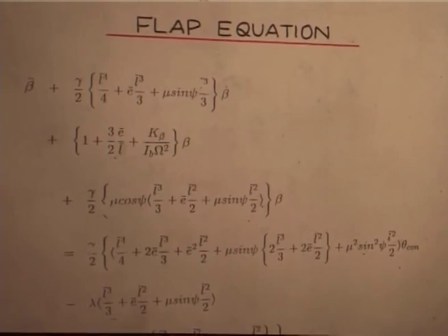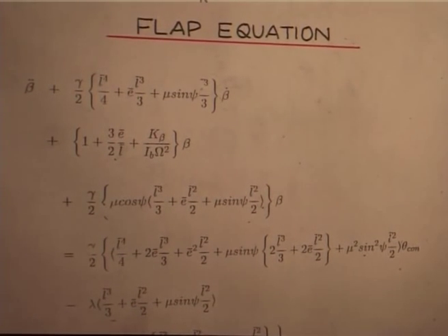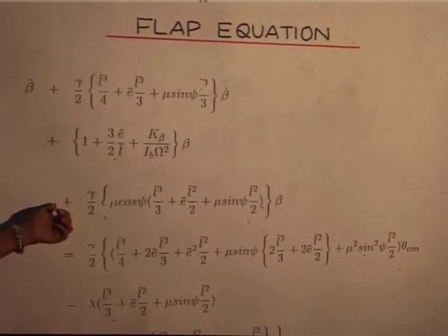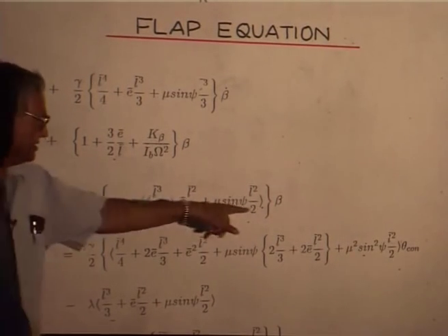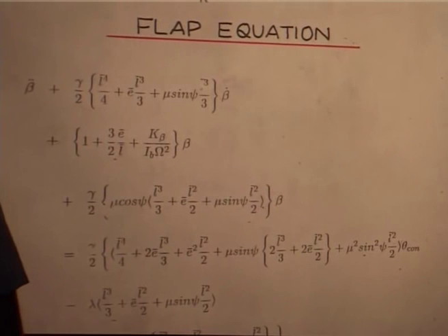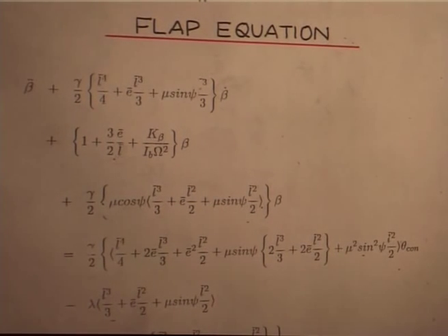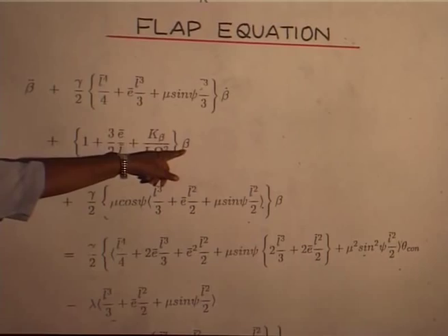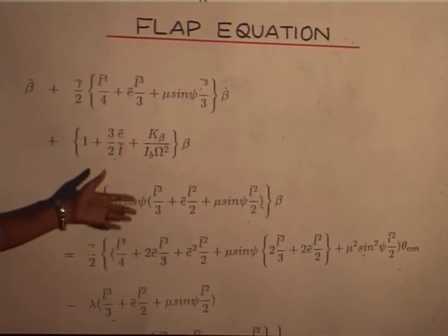Then what will happen? You may have pilot input plus another term which is proportional to the flap deformation. Now, the flap deformation term from here will be taken to the left hand side, because that will come as a beta term. So, you find I can actually alter the stiffness term, because this is related to flap beta, which is a stiffness term.